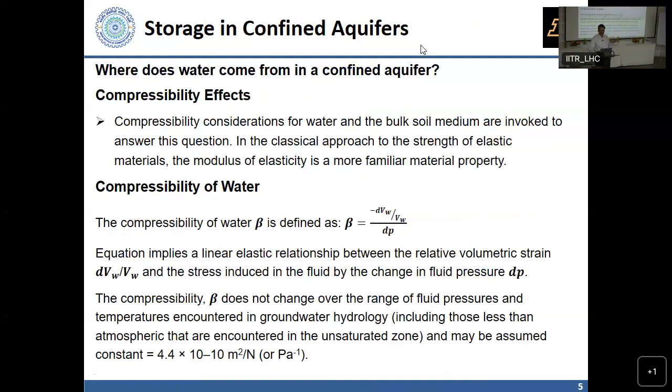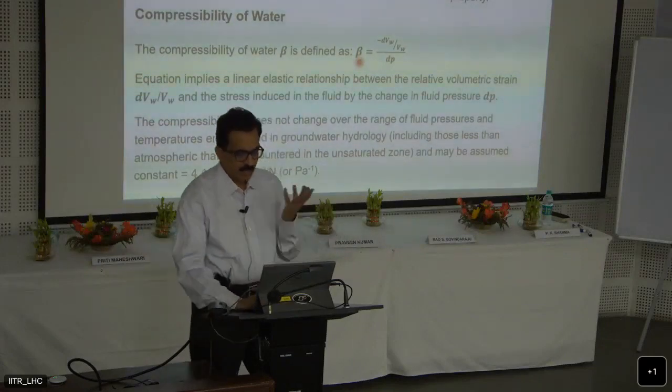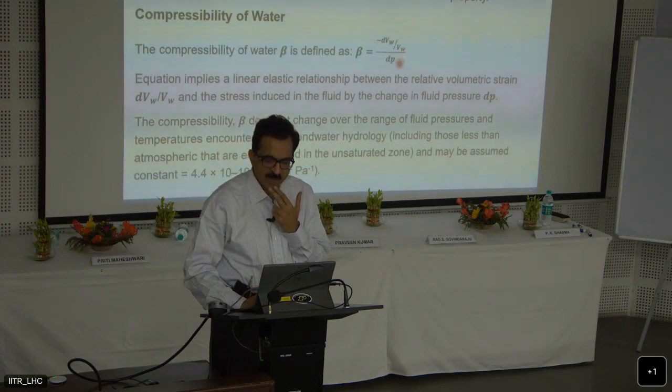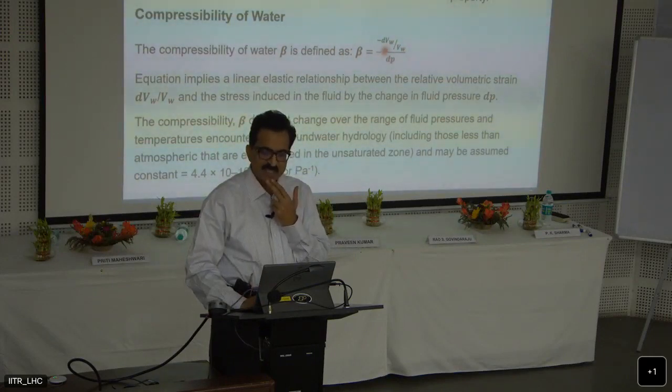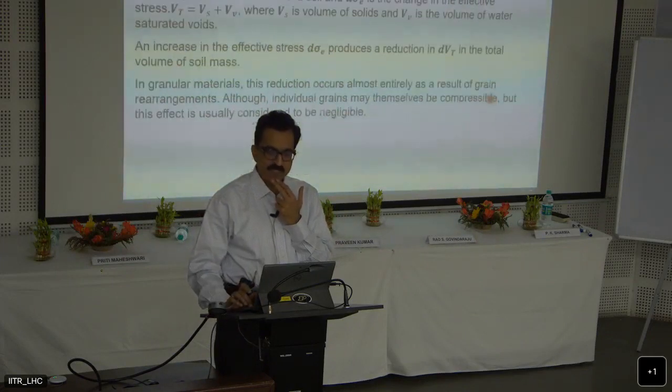So to express compressibility as a positive value, we put a negative sign. It's sort of the reverse of elasticity, compressibility. The negative sign is just because we don't want to say the compressibility is a negative number. It's simply because a positive pressure is accompanied by a negative change in volume. So it's just a convention, no other reason.